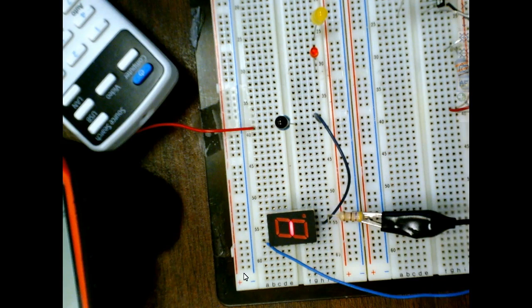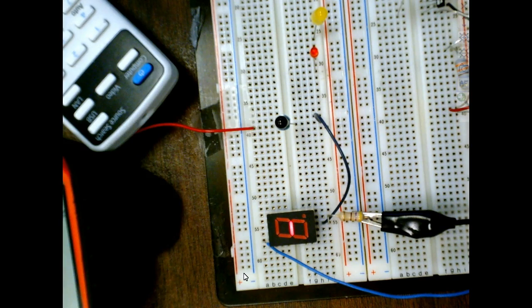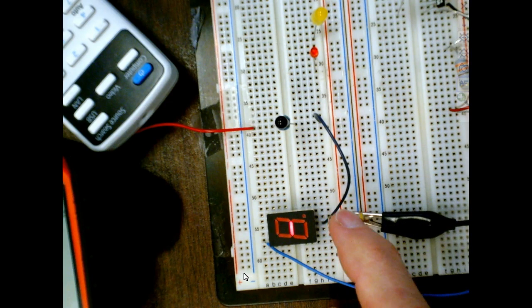We used to put LEDs in the DC trainer. They have one little lab they do DC. What do them knuckleheads do? Well, they get them things on. They look like lights. They'd put them in the power supply, start cranking the voltage up. It didn't work. They'd spin them around. They was blowing those LEDs left and right because they put them across power. We don't put it across power. We got to have at least one resistor.